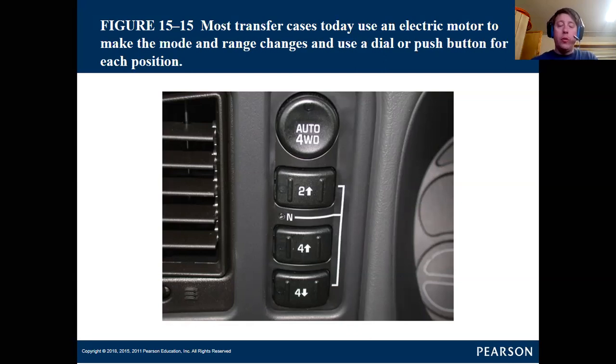So if the rear axle was spinning and the front tires were not detecting any wheel speed, or there's a great distance between RPM, the computer's logic would command that four-wheel drive was engaged.